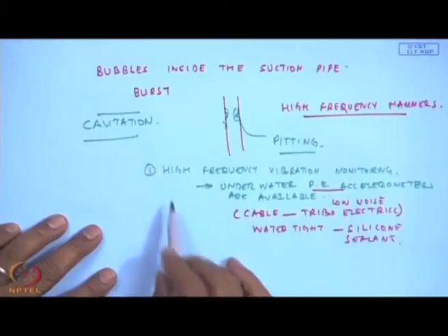Okay. So, we can monitor the vibration because of cavitation on the pipeline, because if this goes unnoticed, they will pit the internals of the pipeline or the casing, and then they will become weak and they will maybe start to leak and then damage.